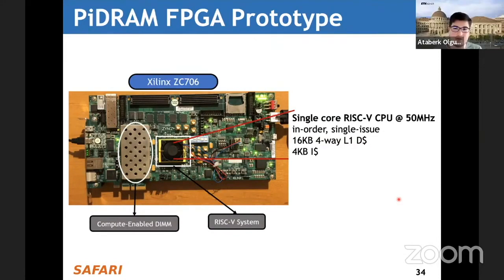Exactly, yes. I didn't talk about it because I think this would already be too long, but to summarize, we implemented D-RaNGe. D-RaNGe is a DRAM-based true random number generator, and how it works is you access DRAM cells with reduced activation latency, which is tRCD. So it's the time window between the activate and the first read command you send to the DRAM row. That results in metastability in some of the sense amplifiers. And if you interrupt the sense amplifier during the sensing process, you will get random values on the bit line.